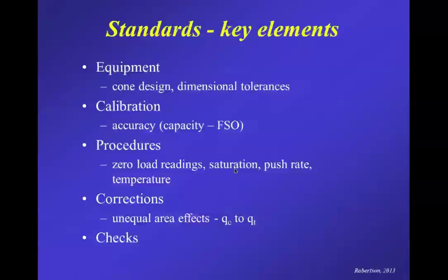They're all pretty good. The key is that you may saturate the cone up at the ground surface, but then you have to turn it upside down and start pushing it into the ground, and you may have several meters of unsaturated soil to get through before you get to the water table, and so there is the issue of loss of saturation. And then if you're pushing through very dense dilated materials, there is the risk that you actually generate negative pore pressures that may desaturate the porous element.